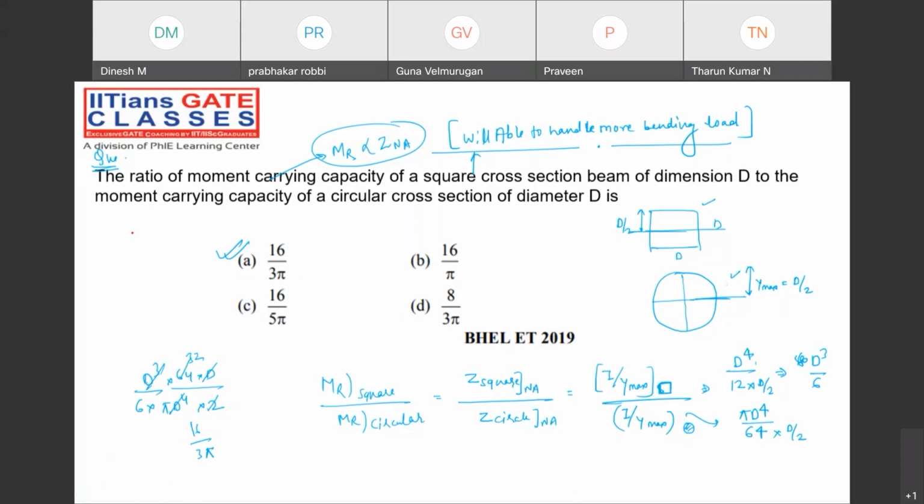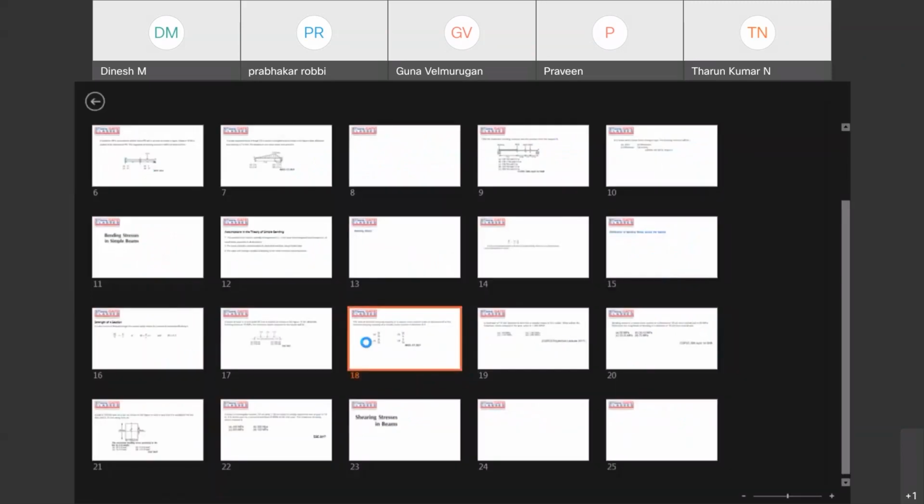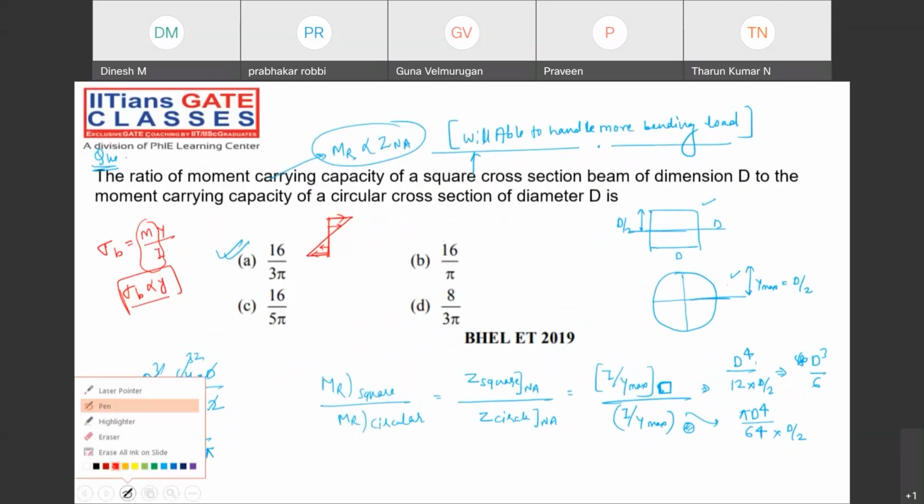Now, you know that the bending stress is what? M by I is constant. So sigma is directly proportional to y. That's the reason it is varying linearly, right? Yes or no, guys? Perfect. Focus. Upper fiber, maximum bending stress is there. Lower fiber, maximum is there. And it keeps on decreasing layer-wise.